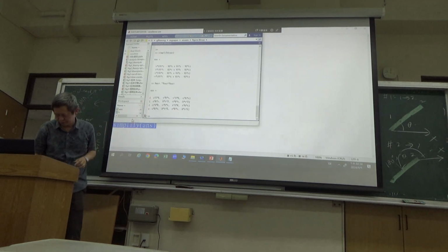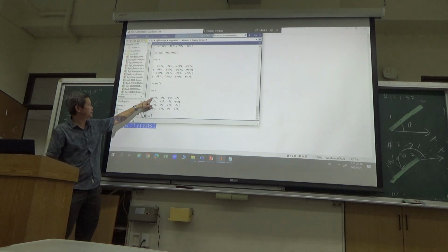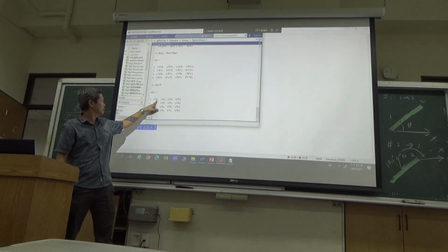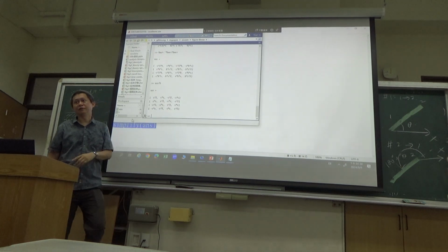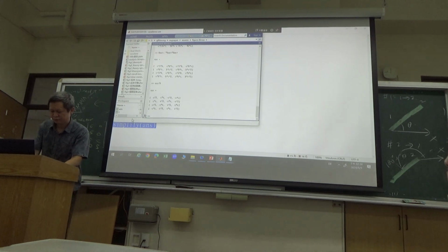So what do you have? And let me see. So you have c squared, cs, minus c squared, minus cs. This is the matrix to be multiplied to the element stiffness. Okay.